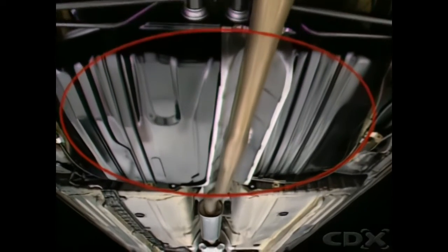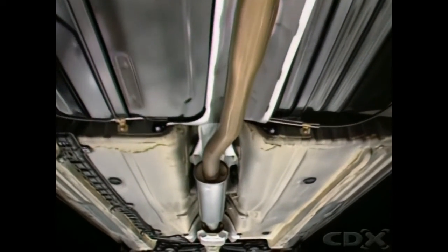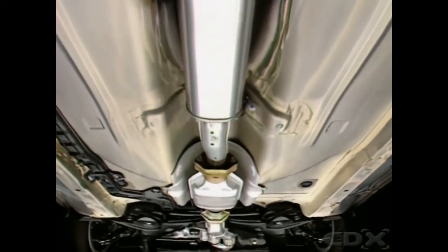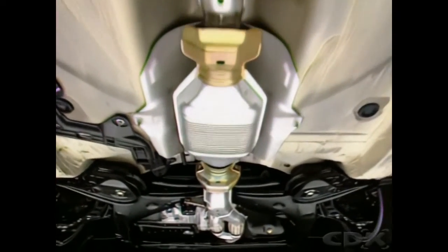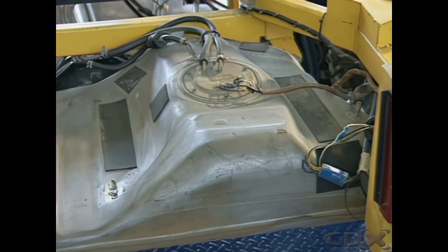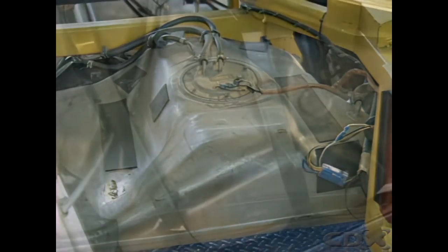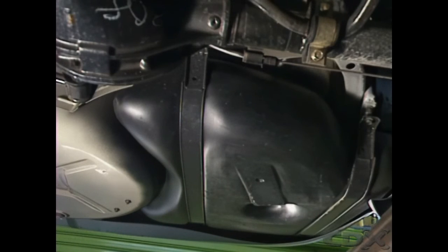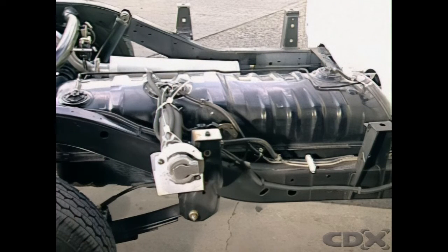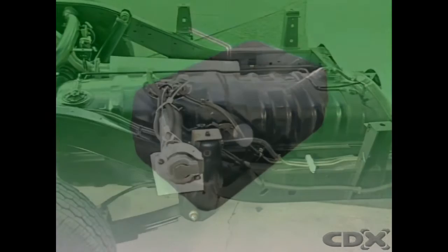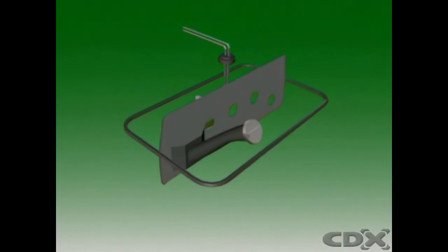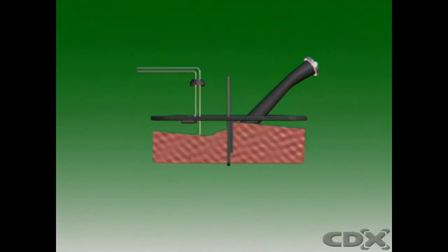Where the tank is mounted depends on where the engine is and on space and styling. Safety demands that it is positioned well away from heated components and outside the passenger compartment. Most tanks are made of tinned sheet steel that has been pressed into shape. Some passenger car tanks are made of non-metallic materials. Aluminum or steel is used on commercial vehicles. The tank is usually in two parts, joined by a continuous weld around the flanges where the parts fit together.